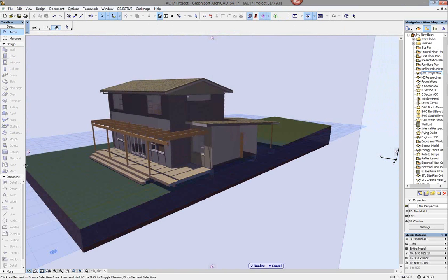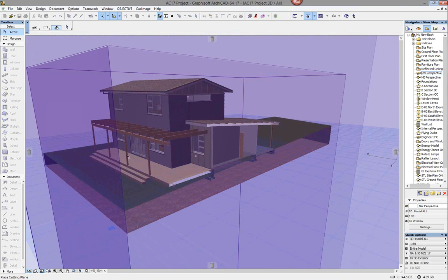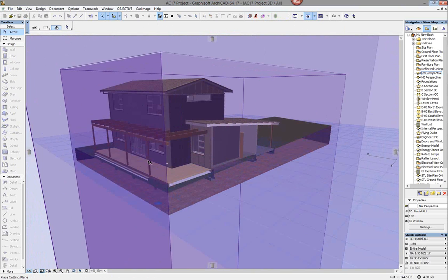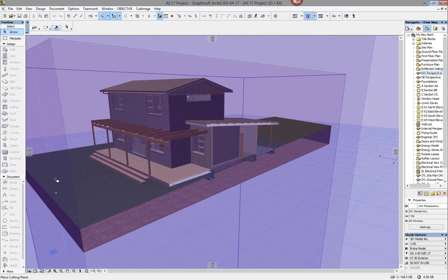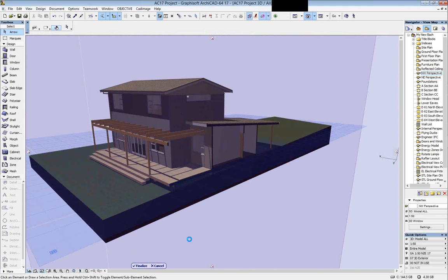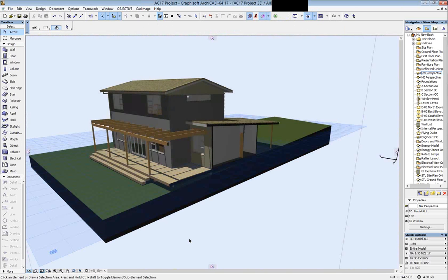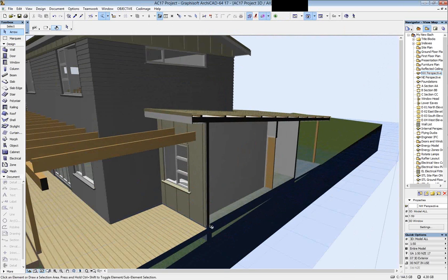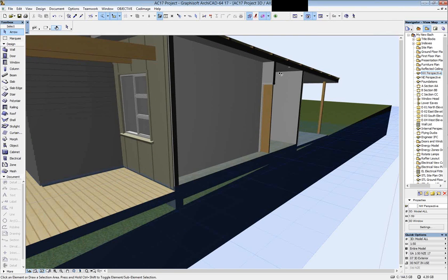Once you finish, you click, then you can drag another plane from somewhere else, and you can just keep going until you show the area of your project that you're most interested in. When you're finished, you can hit the finalize button, and it finalizes the location of your cutting planes, and then you can save that as a view, put it on an output sheet, do whatever you want with it. Now there's some other things that we can do here.